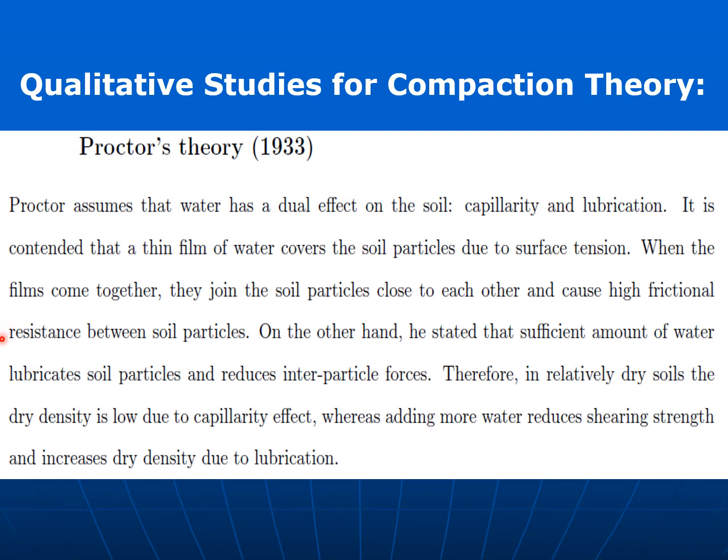On the other hand, he stated that a sufficient amount of water lubricates soil particles and reduces interparticle forces. Therefore, in relatively dry soils, the dry density is low due to the capillarity effect, whereas adding more water reduces shearing strength and increases dry density due to lubrication.